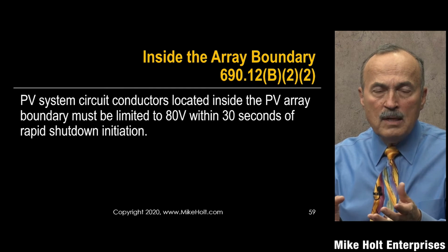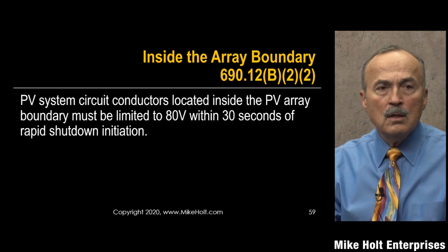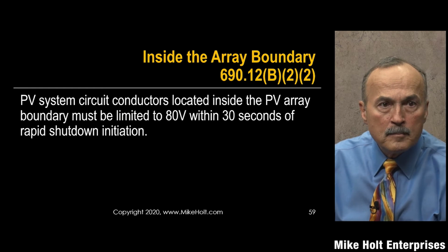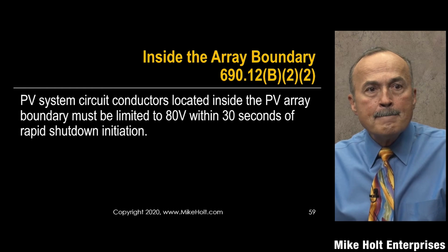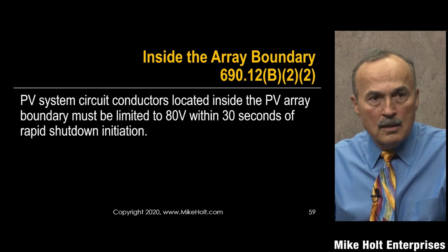How do I know that I have one of these? How do I know if I have a 2? So that's where many people refer to this as module level shutdown. It's not really necessarily an accurate term, but it's the idea that microinverters and DC to DC controllers connected directly to modules would perform this by shutting down their outputs so that the only thing that's left is the input. And we talked about 80 volts because we want to exclude the microinverters, because these are just the DC circuit conductors off of that individual module. And they tend to be lower voltage.